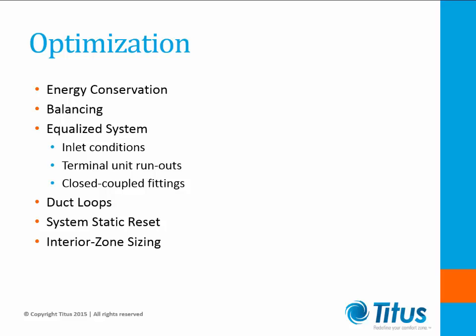Loop ducts are a good tool to minimize both installed ductwork and energy usage. By looping the ductwork, the system can move the air with the diversified load, like a skin load, around the building as the load changes. If separate runouts were utilized per exposure, or some combination of the exposures, the ductwork would have to be sized for the sum of the peaks, and the runouts would require greater pressure to fill them year-round. To where a loop duct, allowing air to transfer from both sides of the duct to wherever the design point was at any time of day, will decrease your total energy usage.